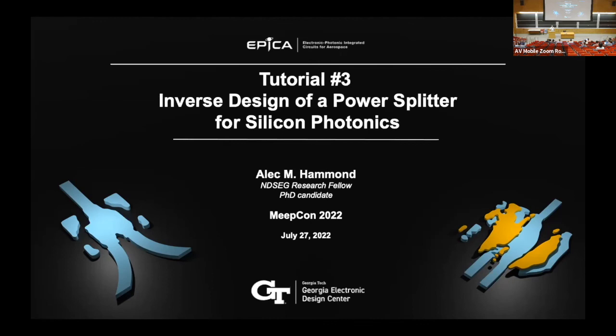that a foundry imposes on our design, right? And do we need to give ourselves a little bit of padding when we prescribe it? If the foundry says it's 90 nanometers, can I just put 90 nanometers in the code? Or do I need to be a little more conservative and say 100, 110, for example? In my experience with hundreds of devices that we've actually sent to the fab, I've been able to prescribe the exact value that they provided, and it's actually worked out. And that's worked for different fabs, not just one particular fab. So yeah, great